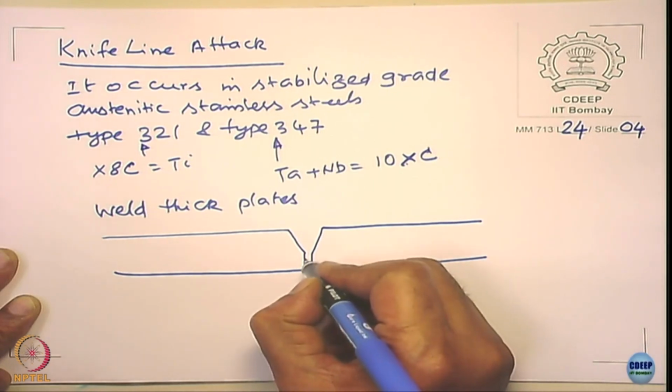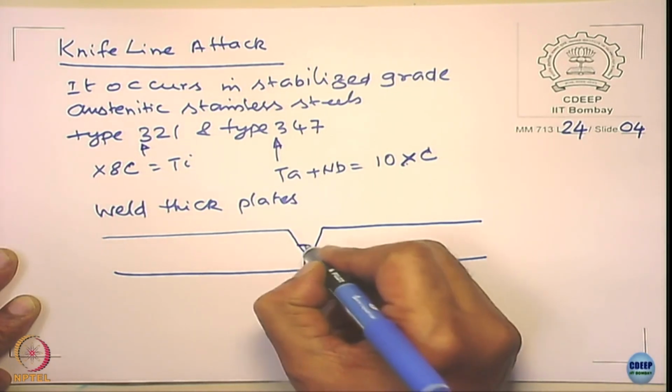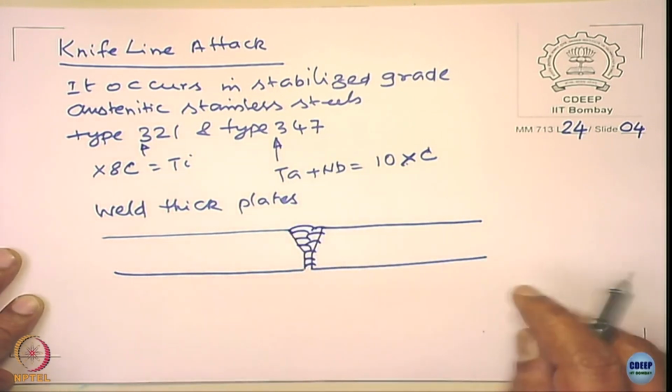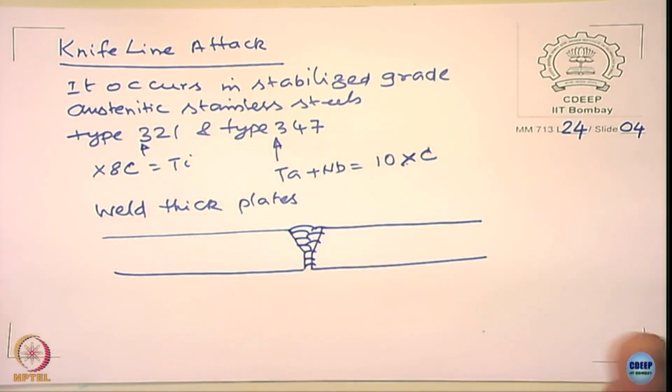So you weld it. As I told you, thick plates require multi-pass welding, without which you are going to lead to sensitization, right?